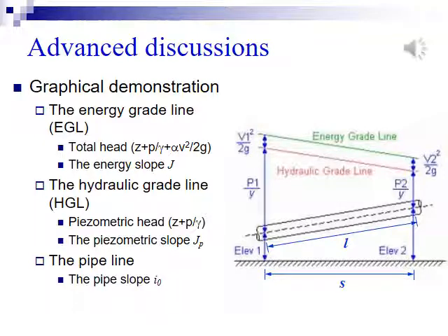In particular, the energy slope J is of great importance to the flow. Energy slope means head loss per unit flow length. Who made it? Yes, resistance did. Therefore, energy slope J can reflect resistances from the tube. The resistance can come from wall roughness, tube narrowness, and even fast running. Yes, that's right. When you run faster, you will feel more tired. So does water.